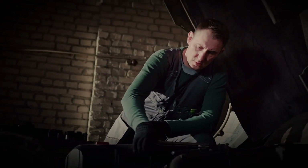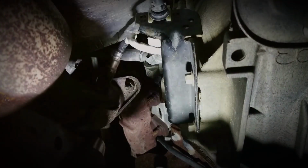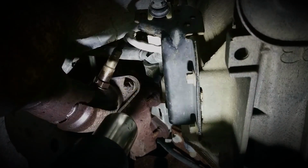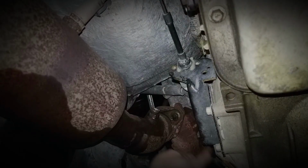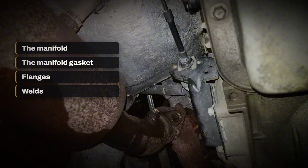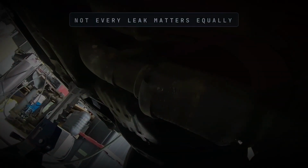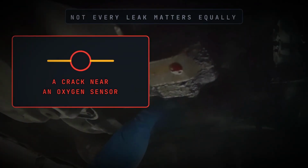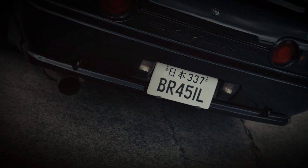Start the engine outdoors and listen during the first cold start. A small manifold or gasket leak may create a sharp ticking sound. That sound may become quieter as the exhaust heats up and the metal expands. Look for black soot around the exhaust manifold gasket, flanges, welds, flexible pipe, and oxygen sensor mounting areas. A crack or leak close to an oxygen sensor is usually more relevant to P0420 than surface rust near the rear muffler.